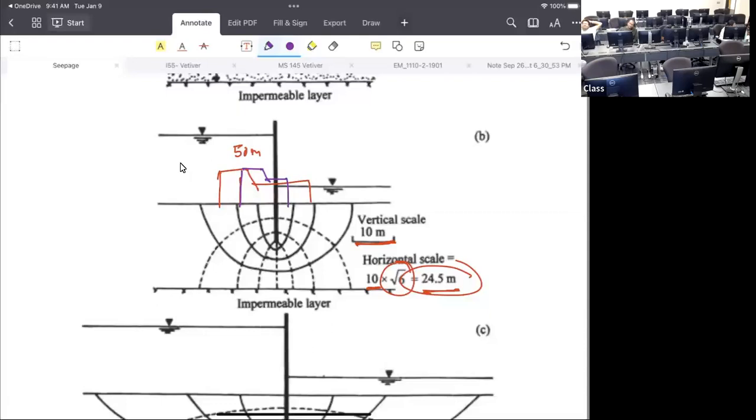It's not a difficult problem. It's just a trick. You just need to know the trick. So many tricks and one problem. Yes, that's true. In this case, now your uplift force has to be calculated. Remember that. If there is anisotropy and there is a dam, then you have to adjust the structure. You have to redraw the geometry of the dam and then do the calculation.